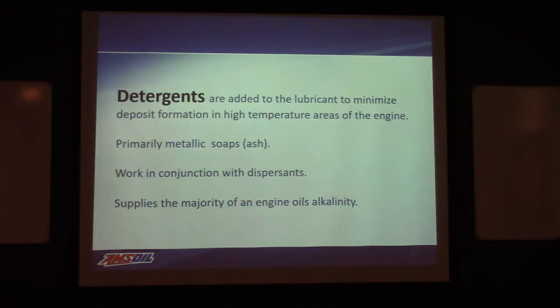Detergents, from a cleanliness standpoint, you want chemistry in there that is going to minimize the agglomeration of contaminants, byproducts of combustion, sludge material, this type of thing. Keep it from adhering to components. And that's basically where our detergent packages come in.